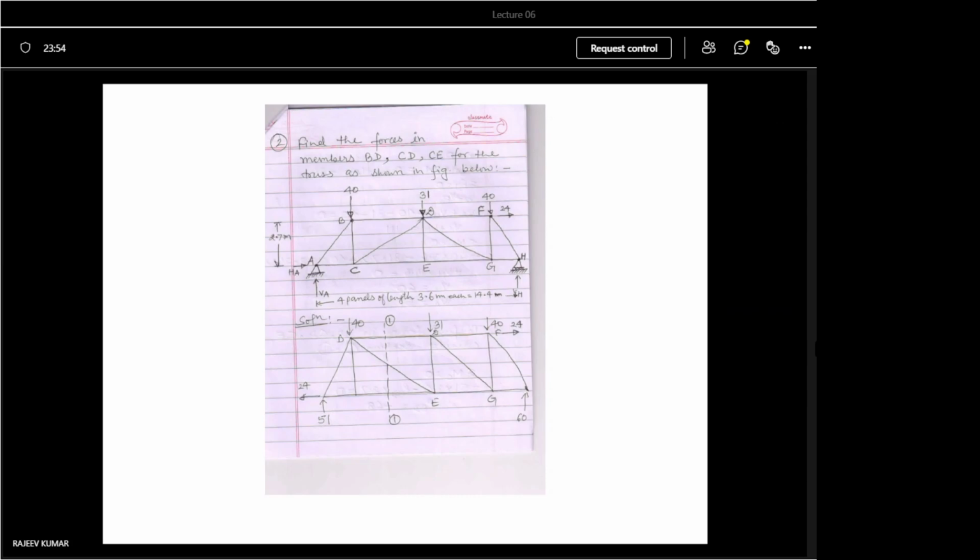The structure is made of material like iron rod, so when contraction and expansion happen, slight movement occurs. If you do not give the gap, it will get cracked or it will bend. That's why we give roller support in the steel structure, or here we clamp it so that by the bolt it can move in some directions. Okay, so this is the structure.